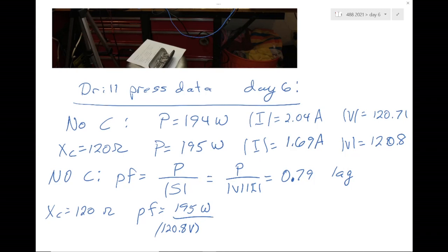There is one thing in favor of it being different. When you improve the power factor, the voltage drop across the wires should decrease. So that 0.7 to 0.8 may actually have happened, but we can't assume that it did. If we were trying to justify putting this capacitor in, it would be hard to do it based on voltage regulation.